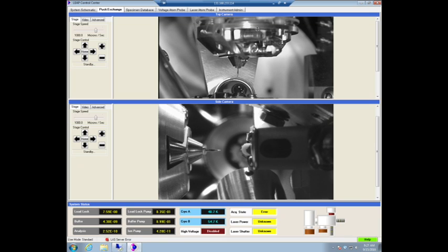If that was to happen, it can partially be because it didn't align the transfer rod properly, or what happens very often is that this was moved to the side, so the last person doing the experiment might have had a sample that was a little bit bent and went out to here, or out to here, and they've moved the whole thing a little bit up. It just goes back. It doesn't go lateral, okay? So the most common error when things get stuck is that the stage is up here or somewhere up here and not right in the middle.